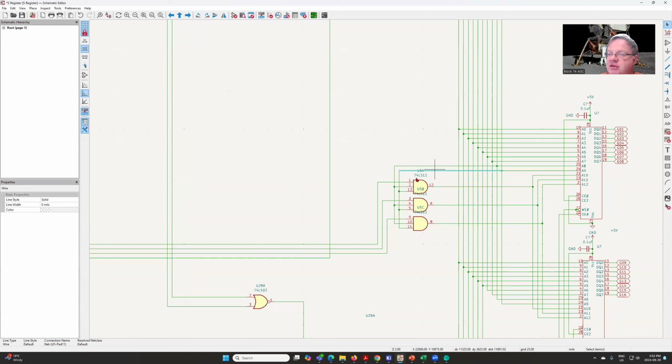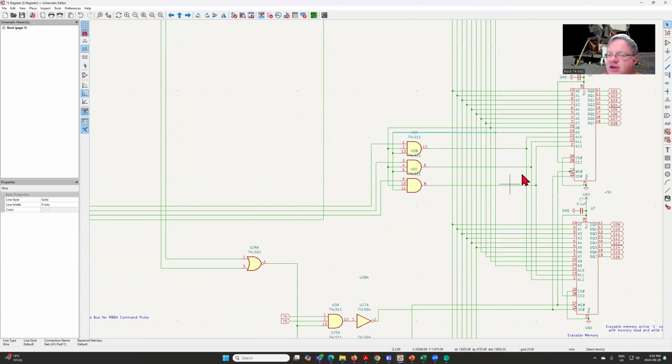If these are not, then basically these will zero out. And so that means we're only going to swap in that bank of memory that we talked about in the last episode. So that kind of takes care of the address decoding. We get the right address that'll show up on our memory chips, and then we can push the data out to or in from the G register.